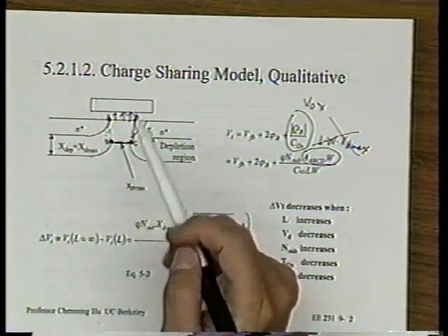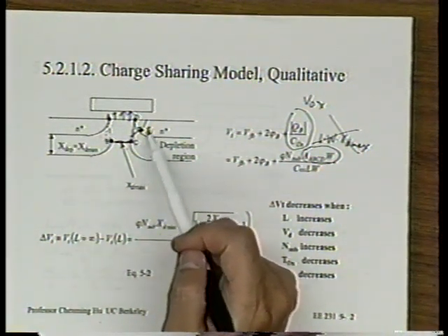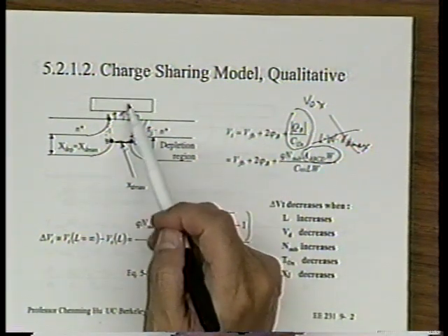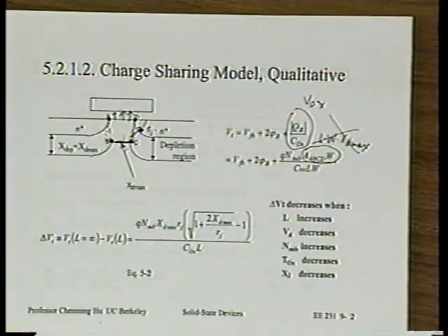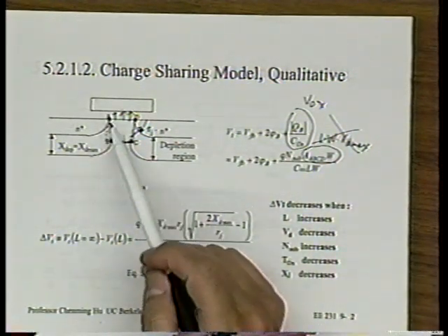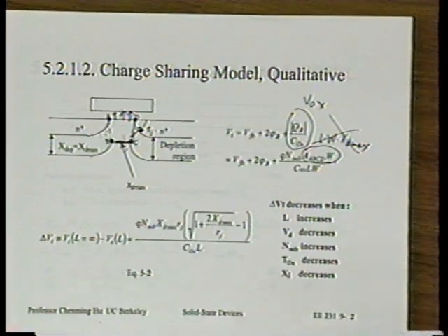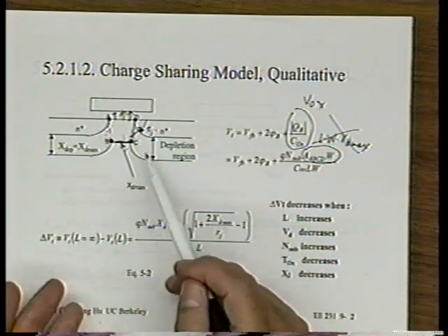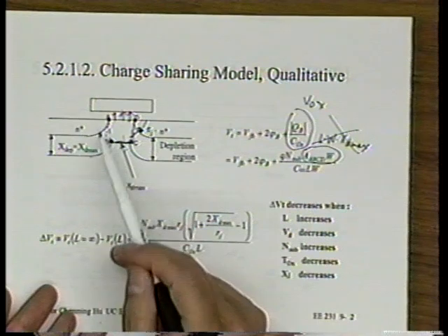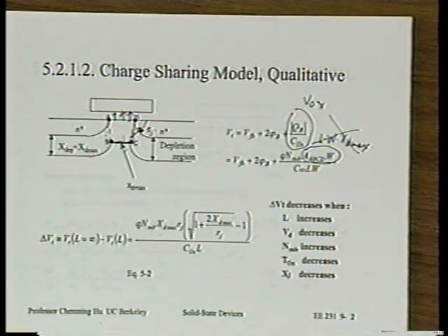Does this charge belong to this PN junction's depletion region, or does it belong to this vertical portion of the MOS system? No one can answer this question quantitatively. This model simply says, let's assume all the charge that falls into the trapezoid ABCD creates Vox. All the charge outside the trapezoid ABCD only creates field that terminates in the source and drain. Now you can determine whether you like it or not. That's all.